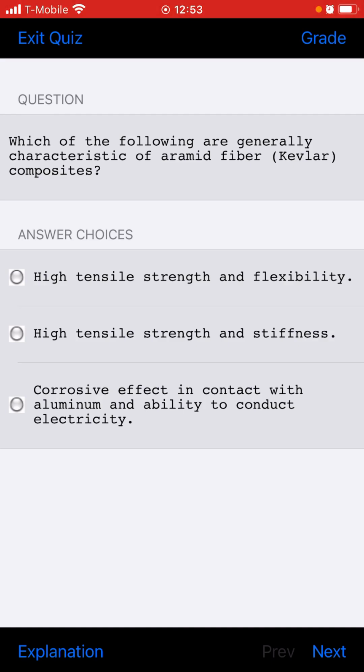When repairing a large flat surface with polyester resin, warping of the surface is likely to occur. One method of reducing the amount of warpage is to use short strips of fiberglass in the bonded repair.